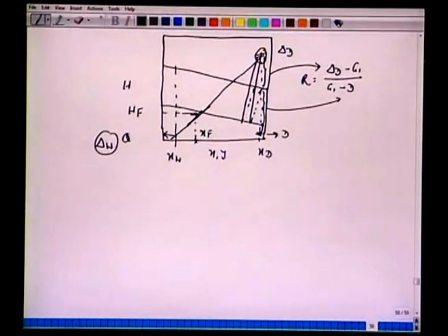So this is what we are trying to say here in the previous slide. This is Q prime, this is Q double prime. All these three points, feed and XW, they have to lie on the straight line. So if we know this point, we know the feed status, enthalpy of this, we connect this, bring to this XW, this point will be Q double prime.